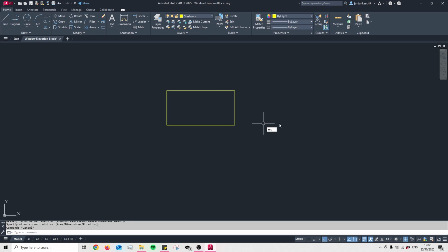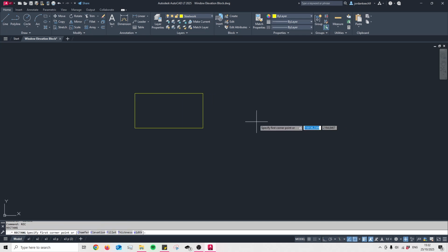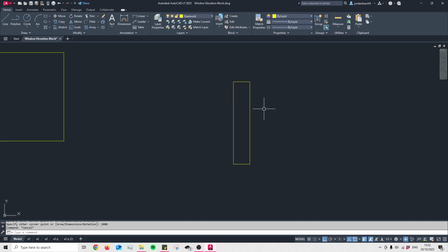To more accurately create a rectangle, you can define the first point using the input fields below, or simply click anywhere once, and then after that you'll see that we have an input field that appears on the length and the width of the rectangle. Type in the desired length into both of the input fields, and the way that we're going to reach the other input field is by pressing tab, and then I can cycle between them and press enter once I'm done, and that gives me a nice precise rectangle.